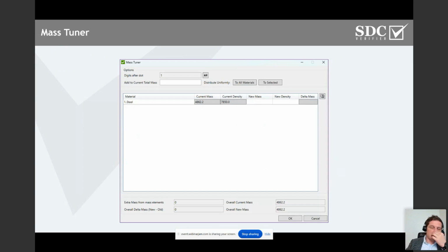It is in the main build of the software release, and this is a very convenient tool to tailor the weight, the mass, or the density of your model without going to the FEA model itself, to material properties itself, and modifying those properties within the FEA software. So in this example, you only see one material, you only see this steel here, but usually in your model, you would have a lot of them, either for different components or for actually different materials.